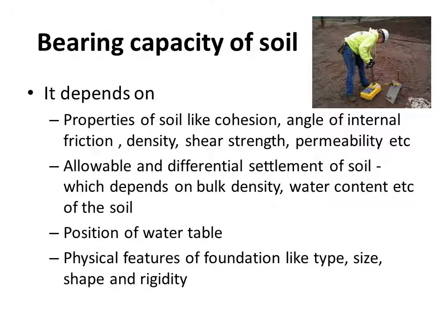The bearing capacity of soil depends on the properties of soil like cohesion, angle of internal friction, density, shear strength, permeability, etc. It also depends on the allowable and differential settlement of soil, which depends on the bulk density, water content, etc. of the soil.